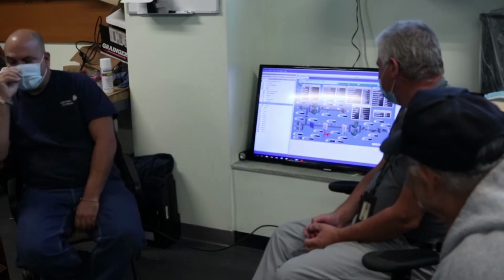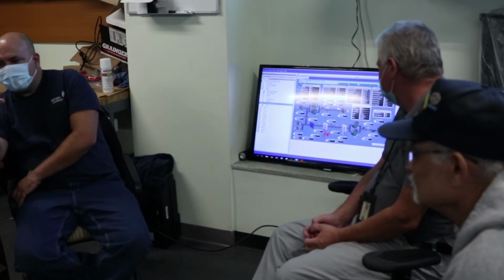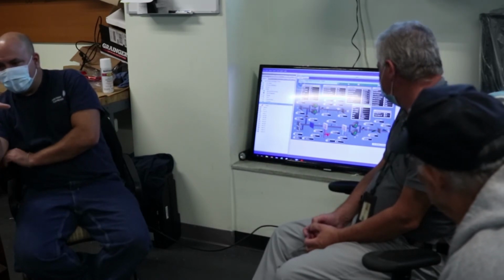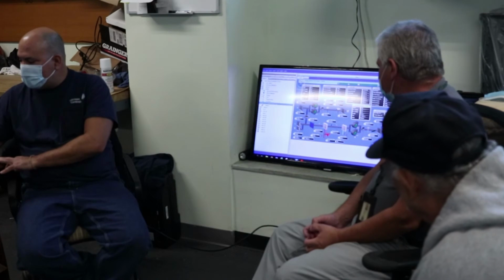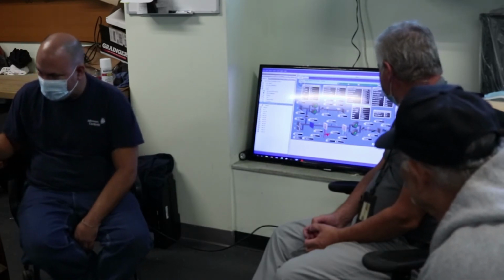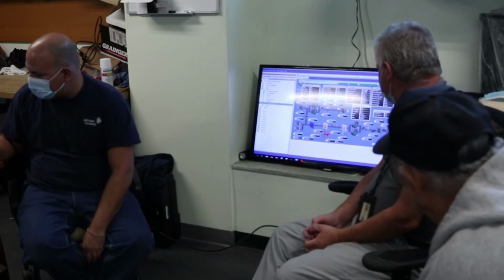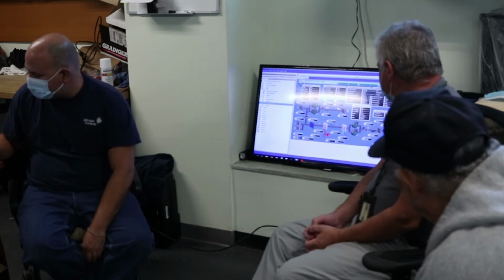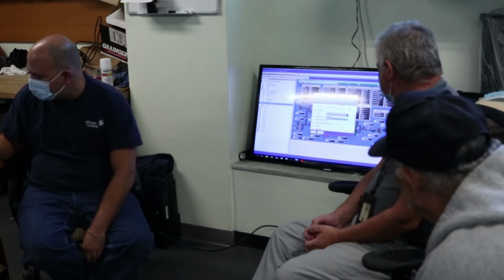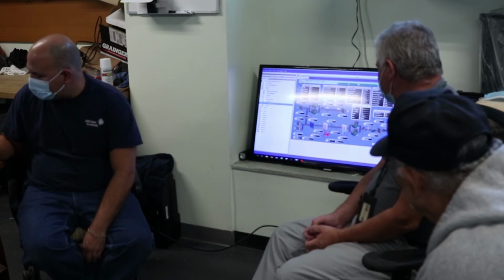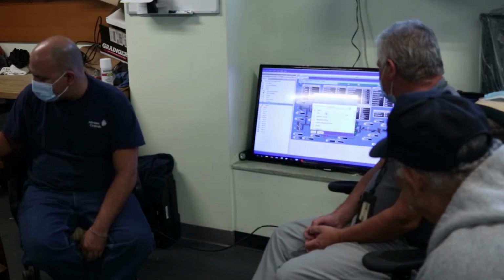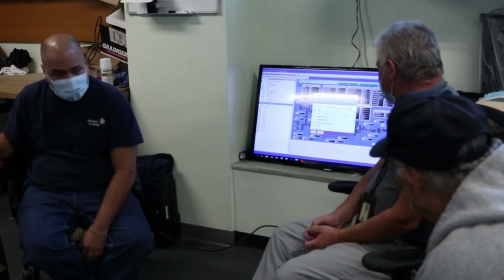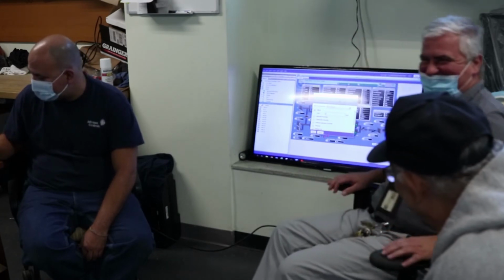It has an automatic reset schedule based on the VAV box positions, right? So that's when it's in automatic. If you want to put it into a manual set point, you have to switch the automatic to manual. And then here's the manual DAT. You can put it to whatever you want. Okay, 95.